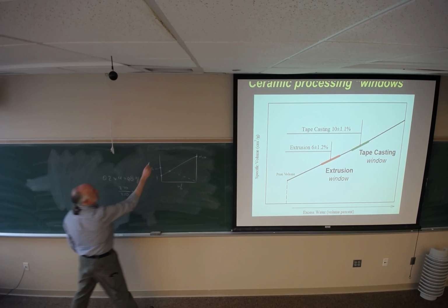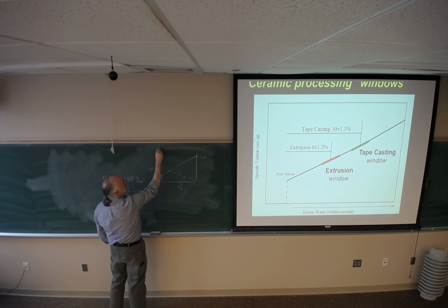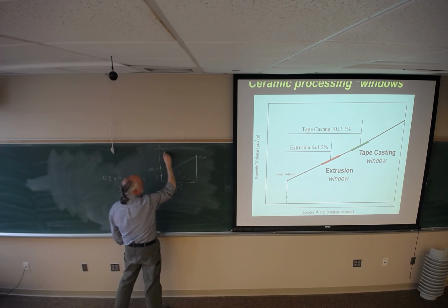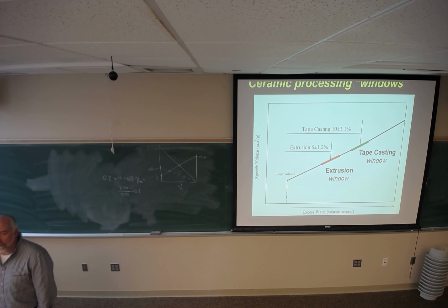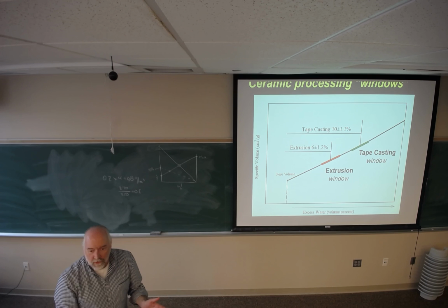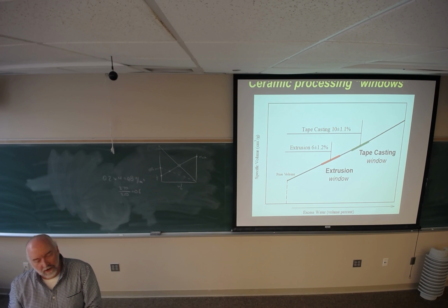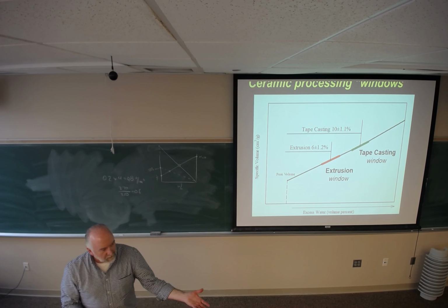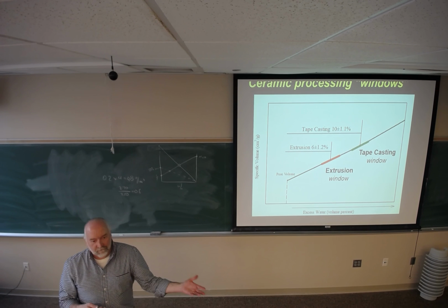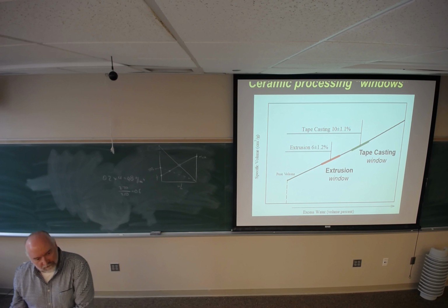That means that if you were to do this dry, your point's up here, right? And if you do this line, you would say that your pore filling is now this huge amount of water, right? What happened? Where have I gone wrong? Because to measure the packing efficiency of the powder, you must be measuring that packing efficiency under the same conditions that you're going to do your experiment. If you're going to disperse the system, you need to measure the packing efficiency of a dispersed system. If you're going to reflocculate it, you need the packing efficiency of a flocculated suspension.